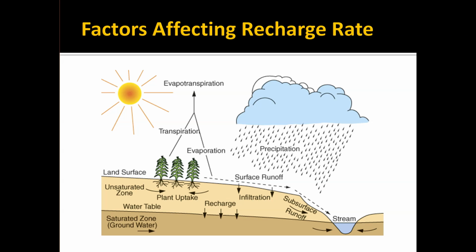It represents the primary source of water to an aquifer. And so the assumption you make can have a big impact, which is kind of scary because we don't really have very accurate ways of estimating recharge. The best we can do in a lot of cases is to do an estimate. I have seen people do surface water models, runoff models to estimate recharge, and that's fine.